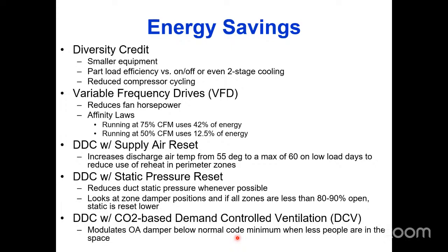And then what the air handler controller does is it looks at all the zones and says, okay, who's the highest CO2 reading? Oh, it's right there, room number 19. Fine. I'm going to use room number 19 CO2 to drive my damper. And if somebody else ever becomes the highest CO2 reading, I'll use that as my reading. It just looks at it and asks, who's the highest number? I'll control to that one. If I satisfy the one that has the worst CO2, everybody else should be fine, right?